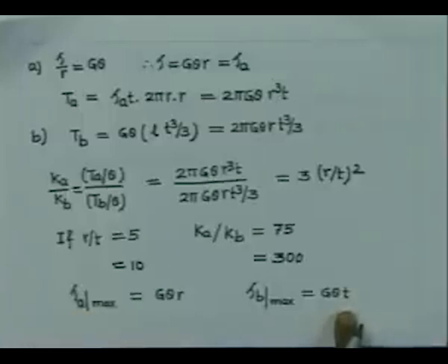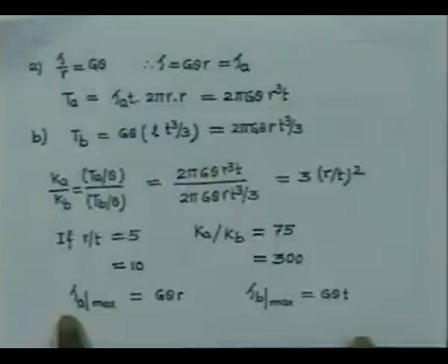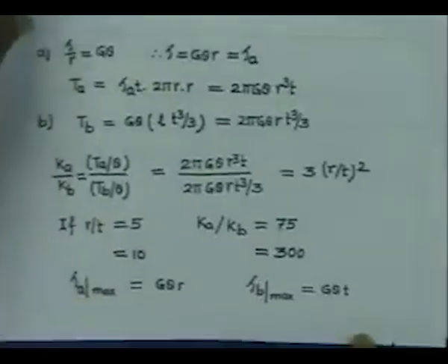So, higher stresses are going to develop, and also you have seen that the stiffness of the closed section is going to be much higher. So, the torque capability in the case of the closed section is much higher, and also the stresses developed are going to be much higher. With this we have illustrated how thin sections can be dealt with very easily.